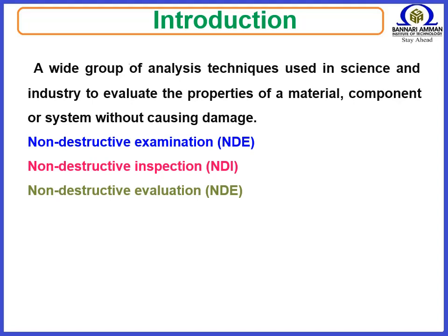Non-destructive examination, NDE. Non-destructive inspection, NDI. Non-destructive evaluation, NDE. Non-destructive testing involves techniques based on application of physical principles employed for purpose of determining characteristics of materials or components and for detecting and assessing inhomogeneity and harmful defects without changing the usefulness of materials or components. The methods used may be simple or intricate. It plays a vast role in quality control of finished product. Skill, judgments and experience is required while performing NDT.